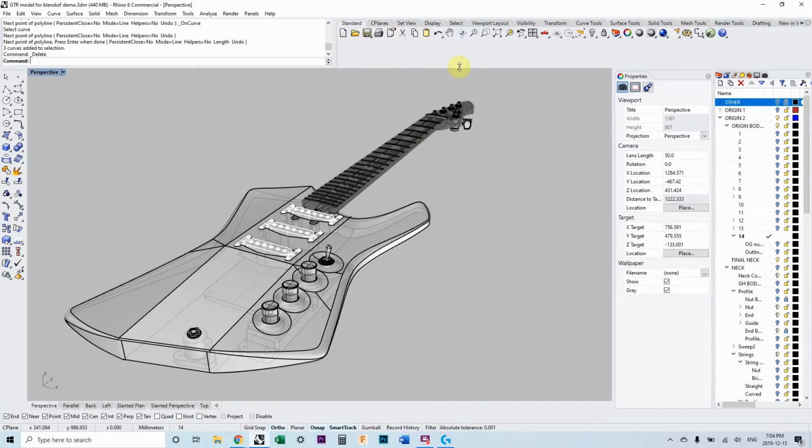Starting off up here, the command panel: I try to make that as short as possible so that I have room for all these icons, but I want a little bit of depth so that I can see the last few lines in the command history. I find that useful when you're measuring stuff or want to see what happened 5 lines back.